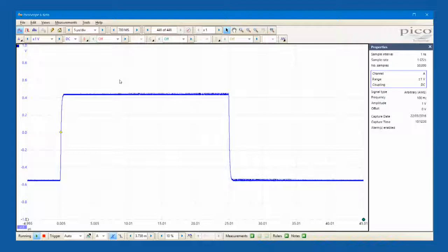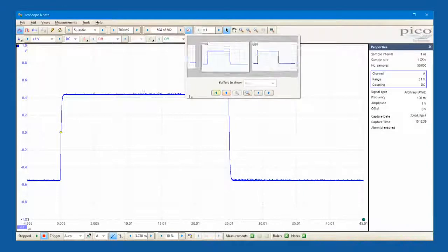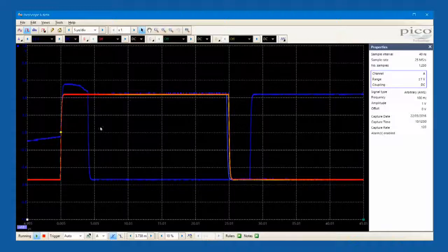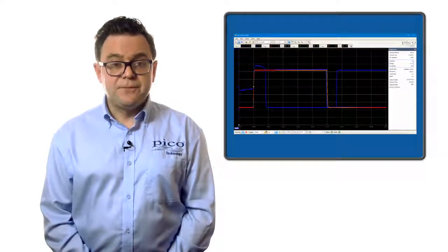You can see the output of these square waves. This is in normal display mode. To investigate a violation, I could scroll through the waveform buffer, but this is not efficient. The traditional way of finding glitches is to use digital display mode, where you have a red trace. This is the signal happening most often, and the blue trace is happening less frequently, which is the glitch.